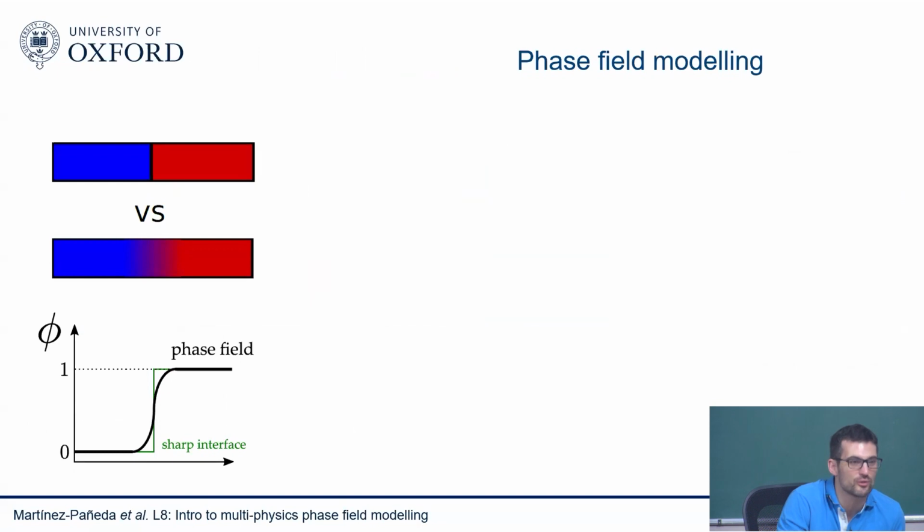The idea is that we can use phase field modeling. In this case, of course, we're no longer talking about intact material and fully cracked material. I'm going to use blue color for the electrolyte, for the corrosive environment, just to make it easier to resemble seawater, and then red is going to be the metal. So we're going to change between phase field being 1 inside of my metal to being 0 in the electrolyte.